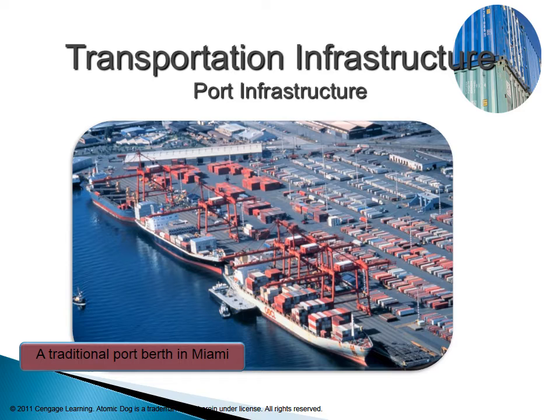Now, this picture shows the Miami port. We see over here those cranes. Okay, we see that in the hinterland we need a huge area for storing the containers. Now, the ship will require some draft. So that's what we talked about, the part which is under the water or inside the water. That's the draft. Okay. Now, each of these ports will have their own operating procedure, operating hours, how many days of the week it will be working, and the connectivity of the port to the hinterland; those are important.